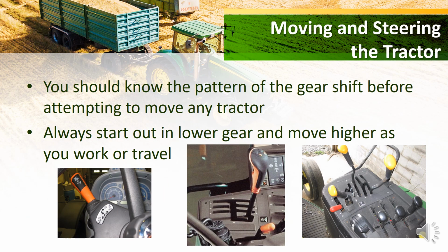When you're moving and steering a tractor, you should know the pattern of the gear shift before attempting to move any tractor. This all goes back to knowing your equipment and reading the owner's manual. Know where your gear shift is, how to move it, and what position things are in. You should always start in a lower gear and move higher as you work.